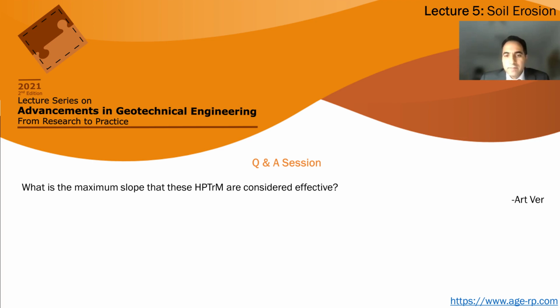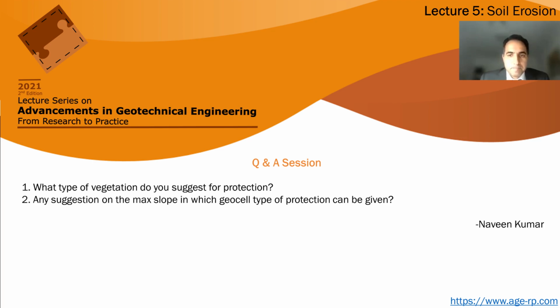That's why we have seen some projects that they design with these products, but they don't think about vegetation. They just think, okay, it should grow. No, we need soil, seed, and an irrigation system. So it's more about vegetation. Of course, for the armoring system, we normally say 45, 50, 60 degrees. It depends on the stability of the surface. If it is going to slope stability, surface stability, we model it to determine. But normally, as I said, it's mainly vegetation that is the criteria.